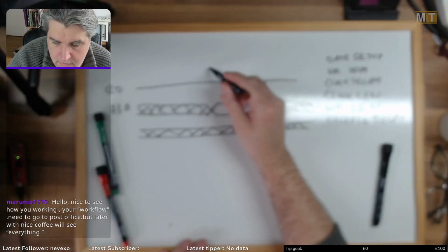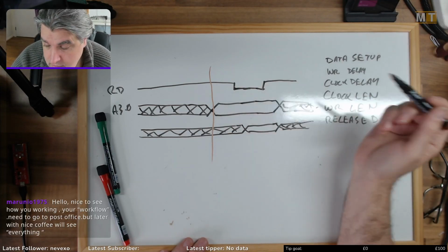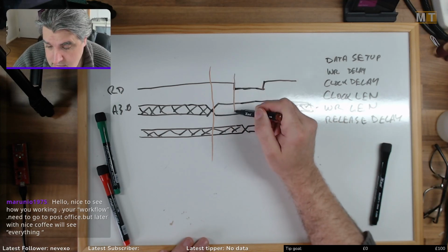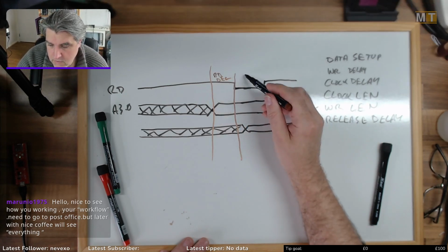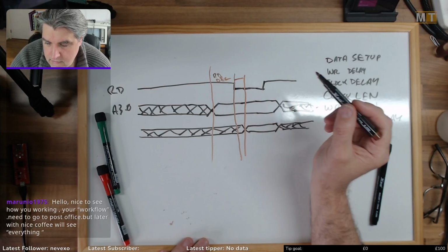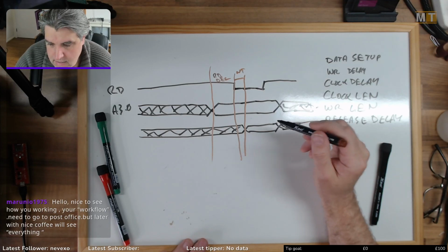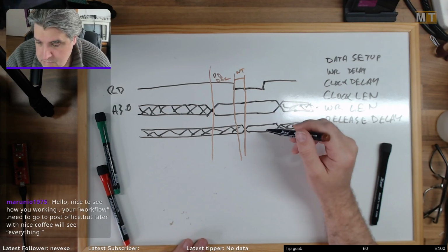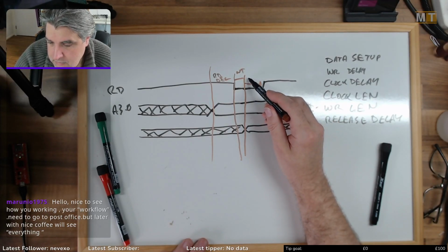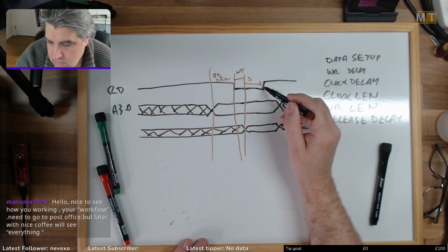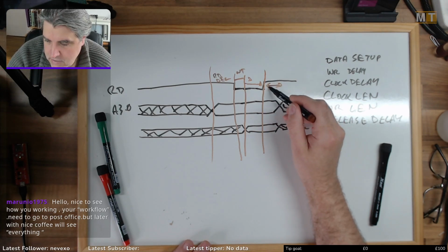So now we have the start time there, and we've got then straight into the read delay, followed by a wait there for the bus data to become stable, followed by a delay there until the read signal rises, and then a post delay there.